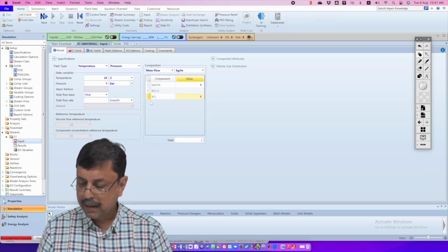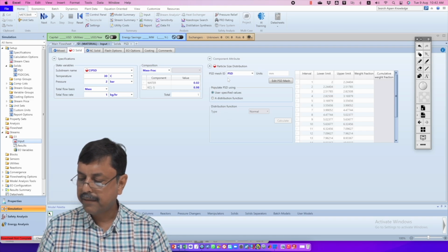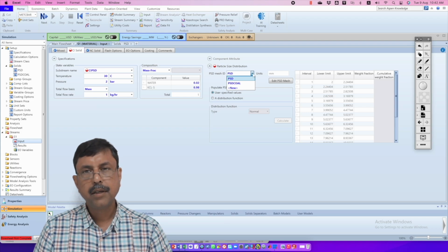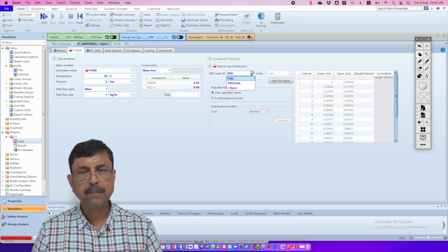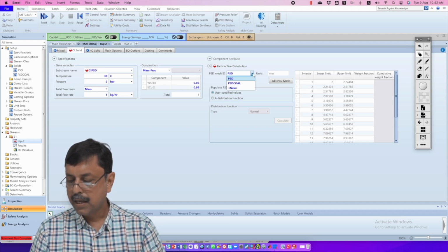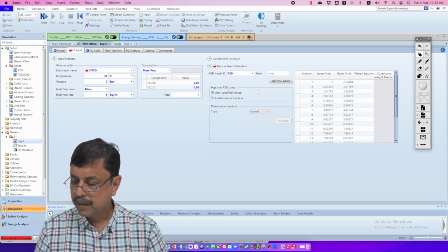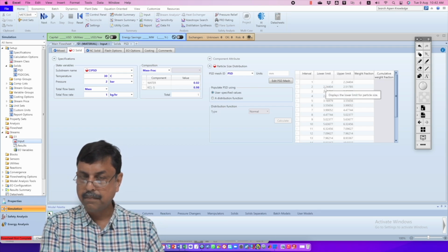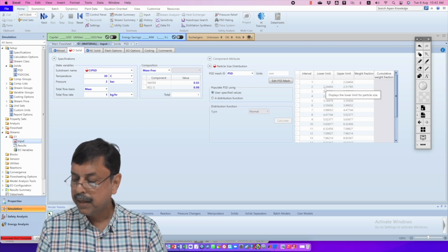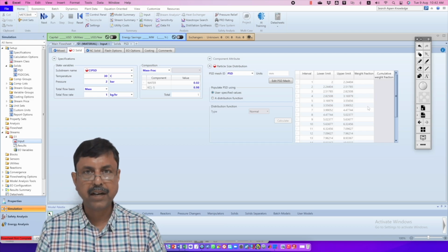and here you see the particle size distribution. There are two options, PSD or PSD coal, that you have created. So here you have the liberty to choose your particle size distribution. Now, let us choose PSD. Okay. So if you choose PSD, then the logarithmic PSD mesh type that you have created is shown over here. And now you have to just put the weight fraction.